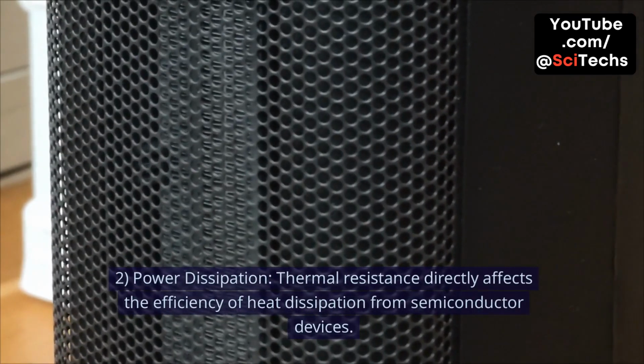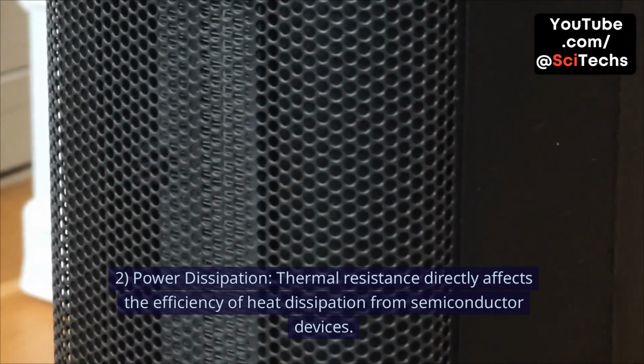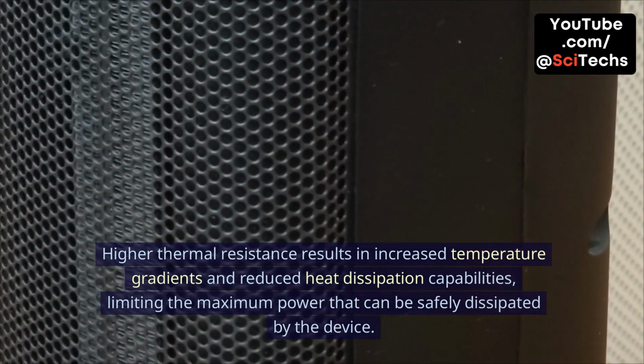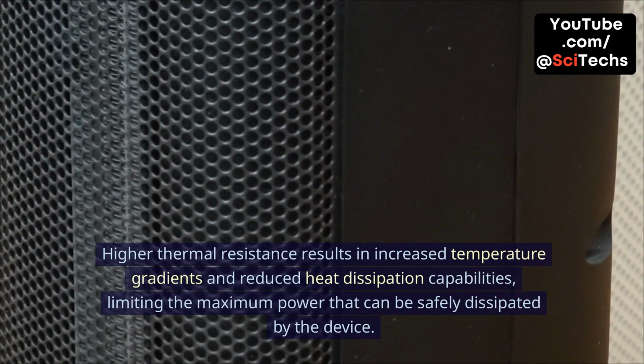2. Power dissipation. Thermal resistance directly affects the efficiency of heat dissipation from semiconductor devices. Higher thermal resistance results in increased temperature gradients and reduced heat dissipation capabilities, limiting the maximum power that can be safely dissipated by the device.